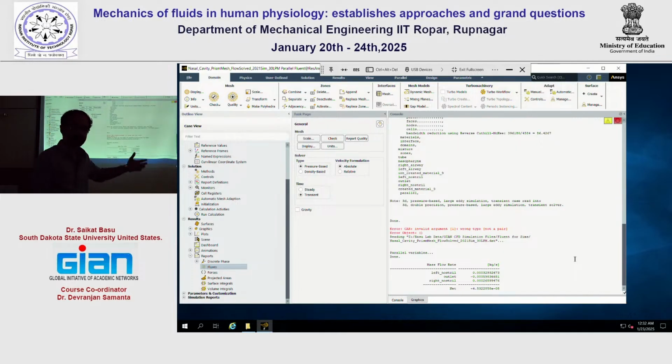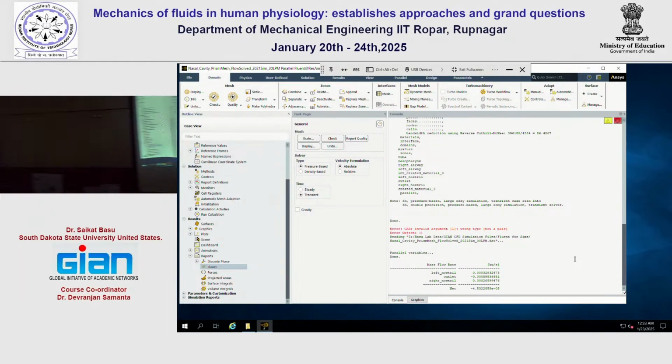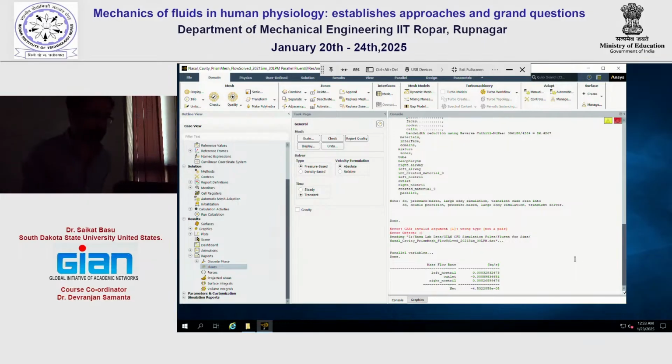So then you might have to redo the simulation, make sure that the pressure values get changed a little bit, and you can also do a convergence, an interpolation study, as in you can run two simulations, figure out which particular pressure values led to what kind of flow rate, and then interpolate those pressure values to figure out at what rough value of the pressure drop you would get a 30 liters per minute flow. But we got lucky here, and many times we do get lucky, and we got an outlet flux that is 30 liters per minute. So you should save this particular window every time you do this kind of work.